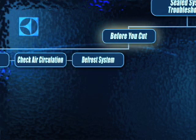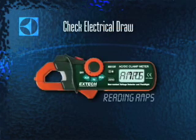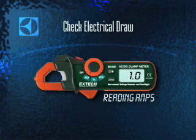If all of these systems are functional, do one more thing before cutting into the system. Check its electrical draw. If it's pulling normal amps, then the problem is not in the sealed system. But if your reading is high or low, get out your process tools.